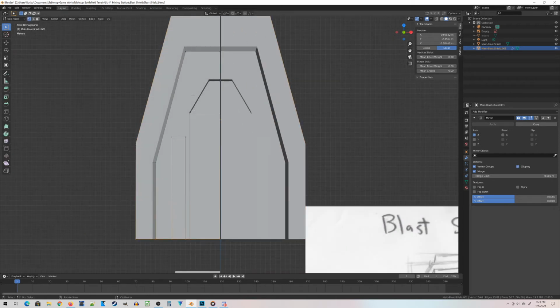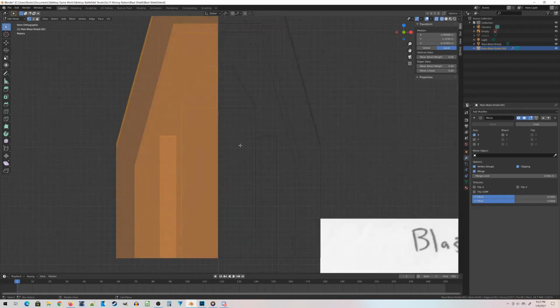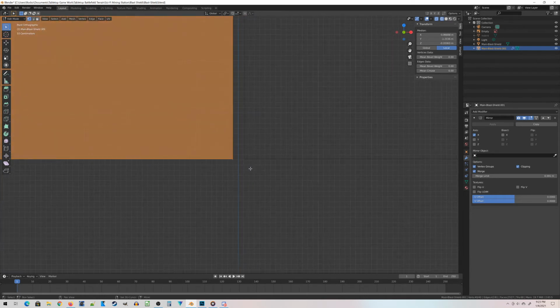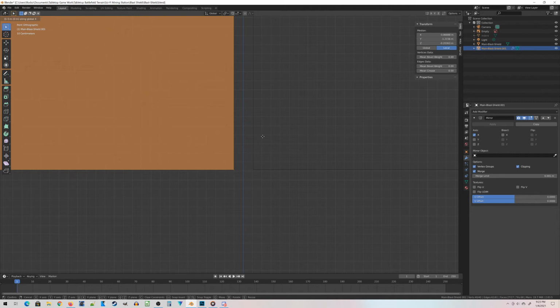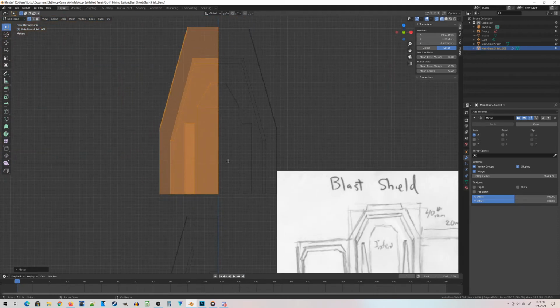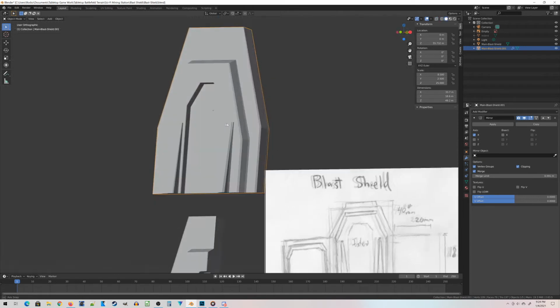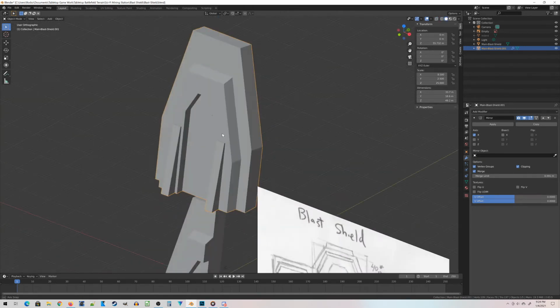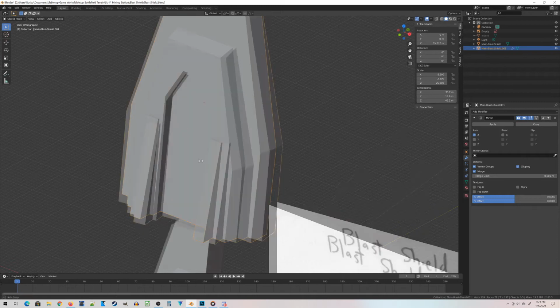And then I'm going to go into edit mode, wireframe, and select everything. Now I'm going to press G and X and move it slowly to the right. And as I move it to the right, its mirror half gets closer from the left, or moves to the left, right? And at some point, they're going to meet each other and not move any further. Because that's what clipping does. It basically moves everything to the center and stops them right there. So now, if I go back to object mode in solid, you effectively have a single piece.